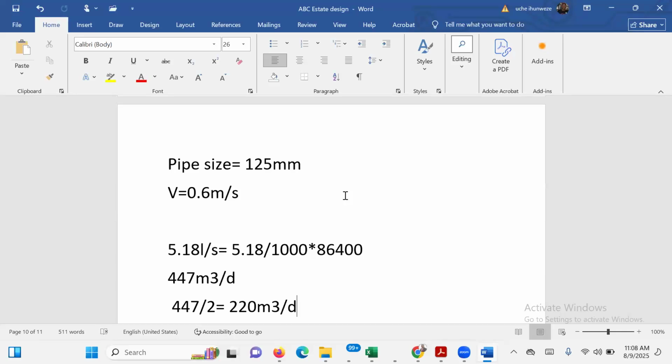So it means the biggest pipe in this network will be a 5 inch pipe or 125 mm, servicing maybe about 100 houses. If you count the whole number of houses there, it's about 100, and you count each house as 20 people. So that is about 20 times 100, which is 2,000. So this is designed for a 2,000 capacity.